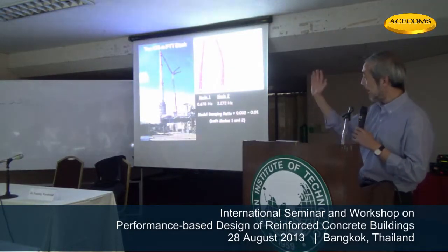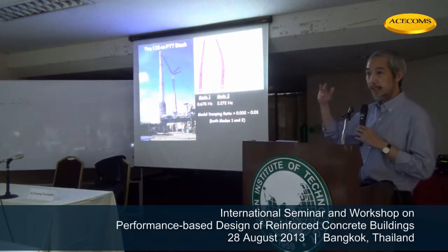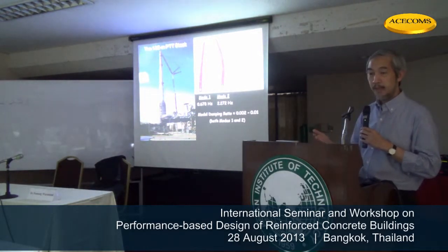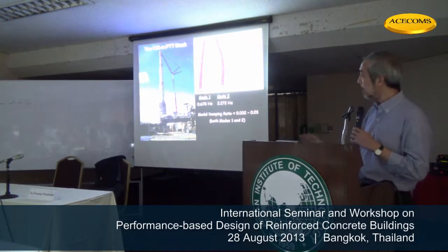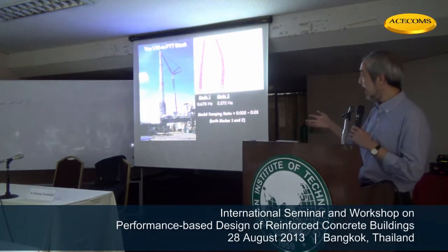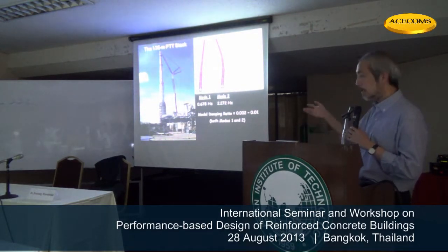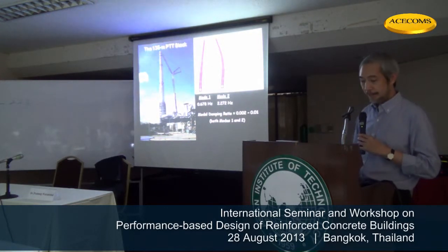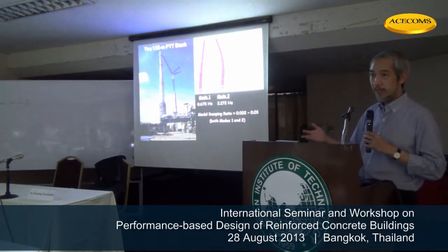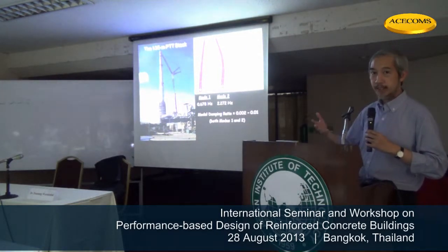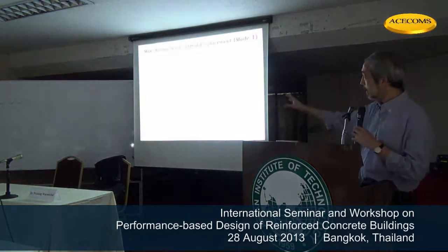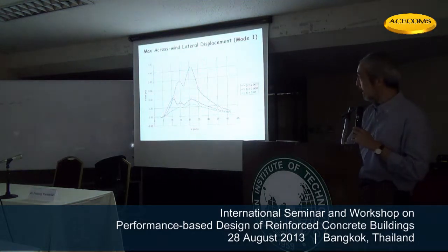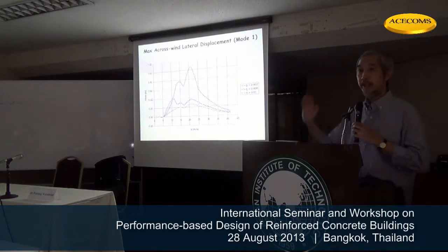From analysis, it showed that the structure may oscillate in 2 modes by wind. The first mode is simple sway with a frequency of 0.7 Hertz. The second mode is about 2. And the shape of vibration is different. But both of them can oscillate in wind. These are our analyses. They show, for different wind speeds, this is the amplitude of oscillation.